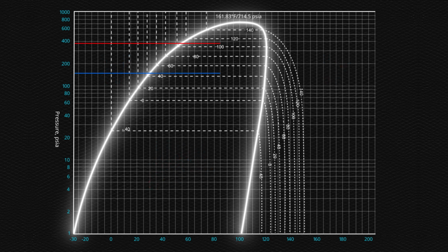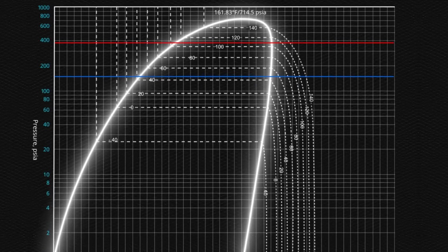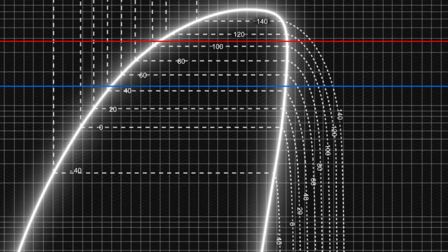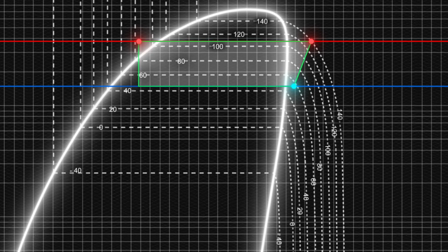Begin by drawing a line for the saturated temperatures. Mark the refrigerant temperatures at the compressor inlet and outlet. Mark the inlet temperature of the TXV. Finally, connect the lines. The compressor increases the pressure, temperature, and enthalpy. The refrigerant has the highest energy at the compressor outlet.